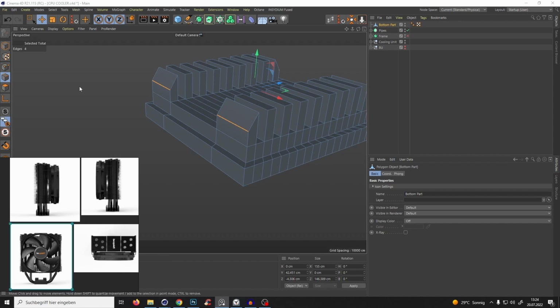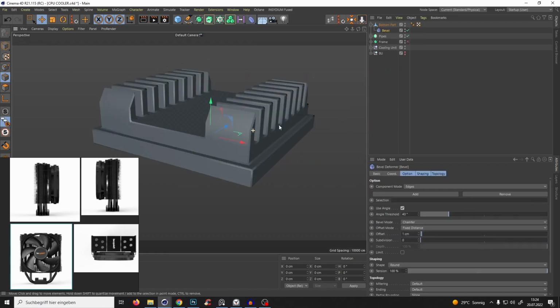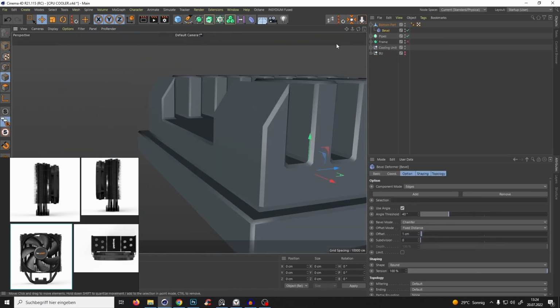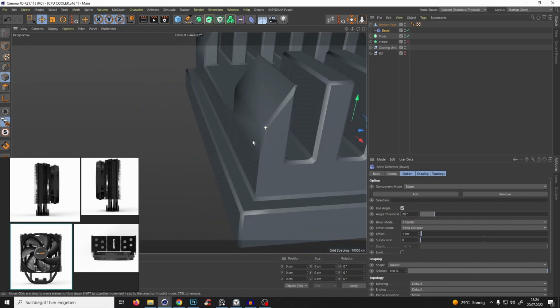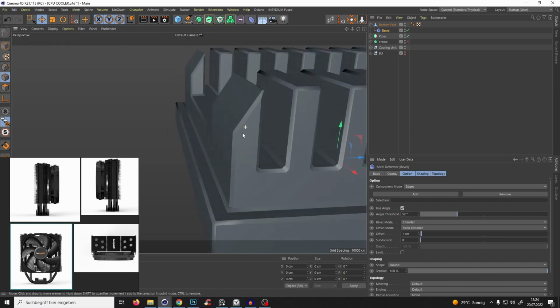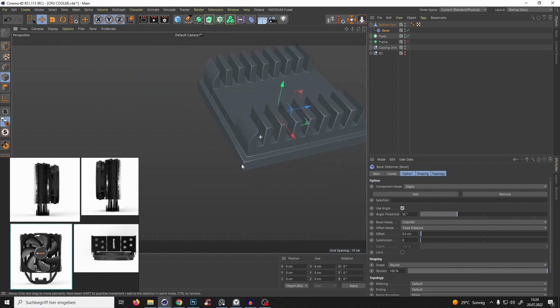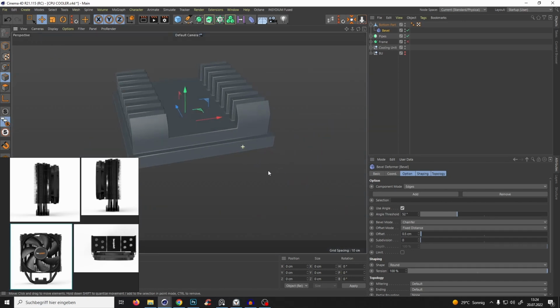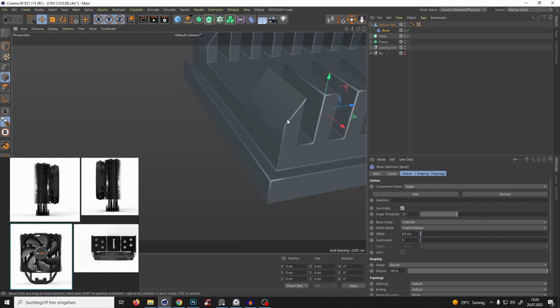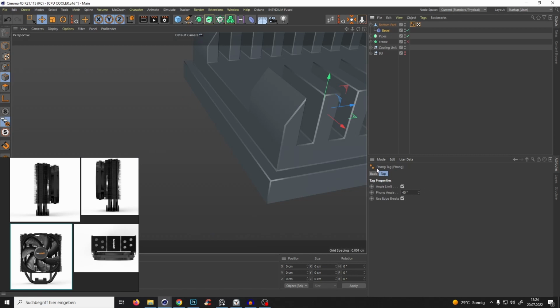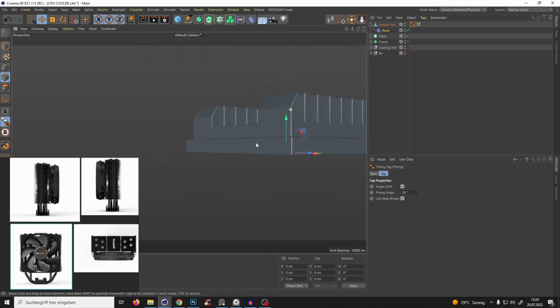yes, bottom part. Again, deformers, shift click for the bevel. And let's play with the threshold a little bit, make it a little bit smaller maybe. And yeah, we have something like that, and yeah, that's for the tutorial enough. And if you want here a hard edge, as you see it here, you just have to go to the phong tag and just bring this a little bit more down. So yeah, you have something like that.